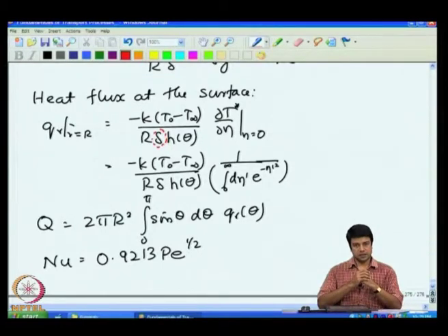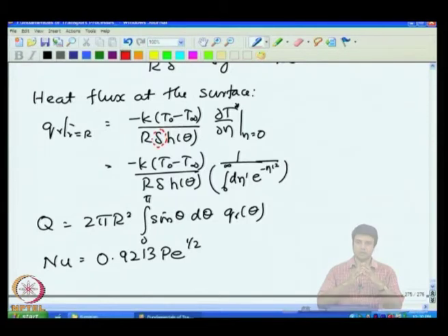The coefficients in the Nusselt number versus Peclet number correlations can be determined by doing boundary layer theory and similarity solutions. In the case of flat plate, the similarity solution is quite straightforward for parallel flows. For flows past objects, there is actually a boundary layer, a wake at the back where the boundary layer thickness goes to infinity. We did not go through the details of the flow in the wake. Suffice to say that the transport in the wake does not really affect the scaling, because the heat flux in the wake region is small compared to the heat flux everywhere else. And that is a brief summary of high Peclet number transport.